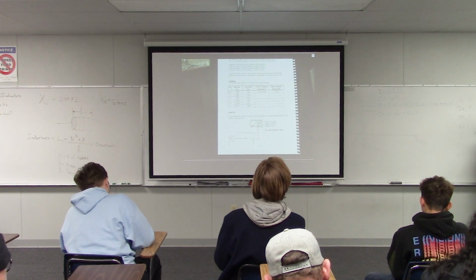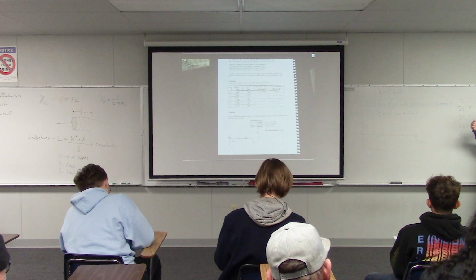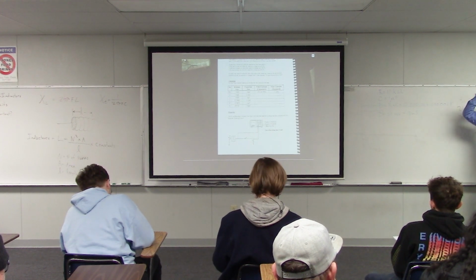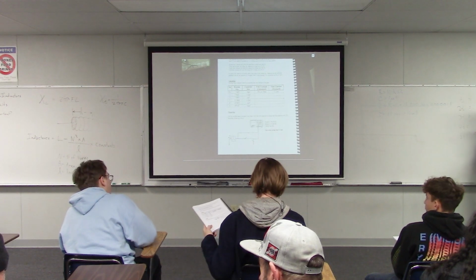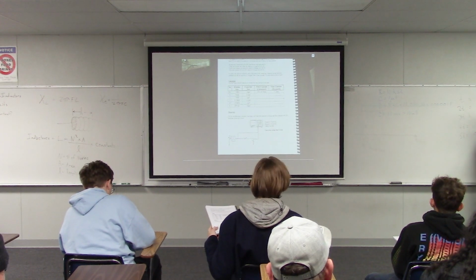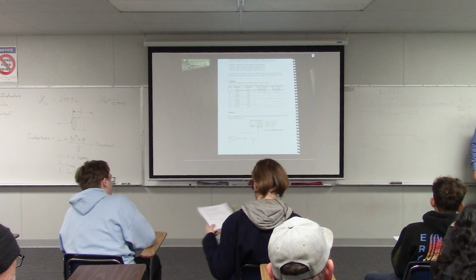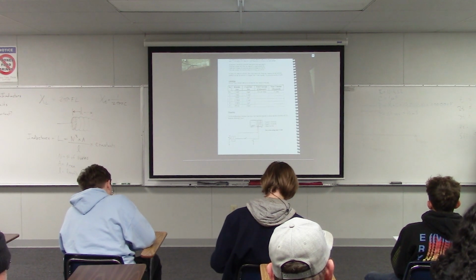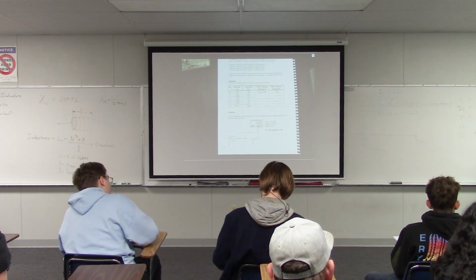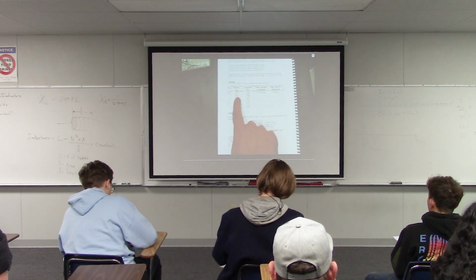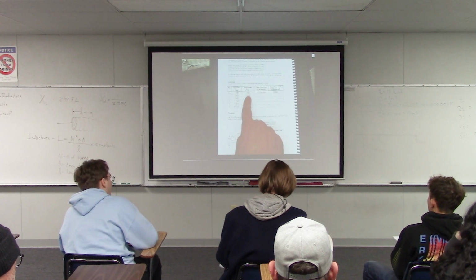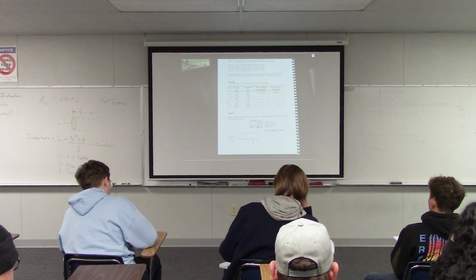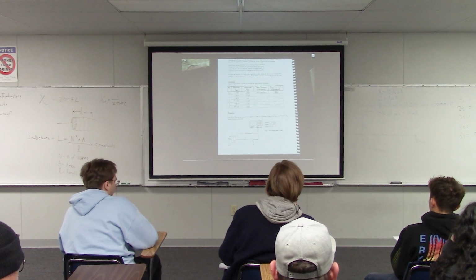Does that seem right? Is anybody else getting the same numbers? Yeah. Yep. I'm just trying to figure out, where did the 10 kilo ohms and the 1 microfarad come from? Those happen to be the resistor and capacitor that I brought with me. Oh, gotcha. Okay. So when you're doing it, for the first one, you'll use a 1 kilo ohm and a 2.2 microfarad and do the calculation that way. Okay. Other questions?